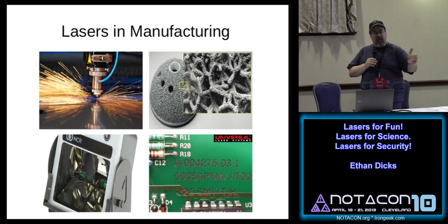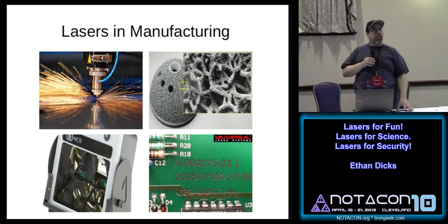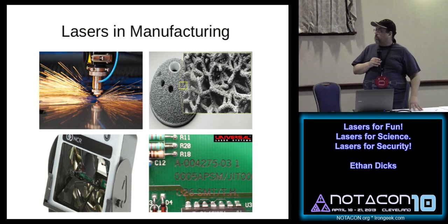You then apply a new layer of material, and you hit that layer with a laser, it fuses to the layer below it and to itself, and you build up the item one layer at a time. But instead of like a MakerBot, which extrudes hot plastic, laser sintering takes granular material and builds it up, and you can work in metal, which is very handy.